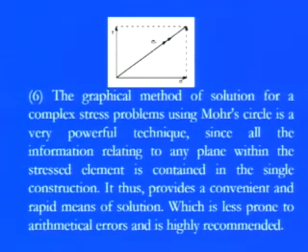Now this is the beauty of this analysis, that we have all kinds of flexibility to put the points. If you want to calculate sigma x or sigma y or tau xy, or if you have these values, you can easily go for the principal planes sigma 1 and sigma 2. You can also find where the maximum value of sigma 1 is, where the maximum and minimum values of sigma x are, and where the maximum and minimum values of tau xy are, just by rotating the elements.